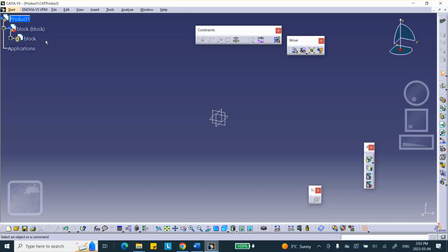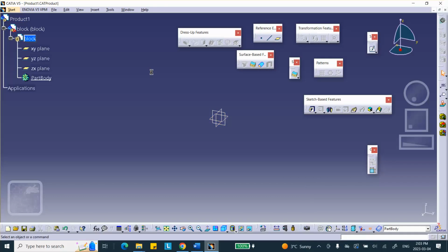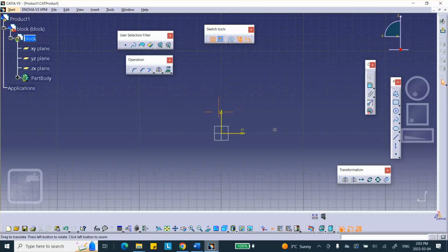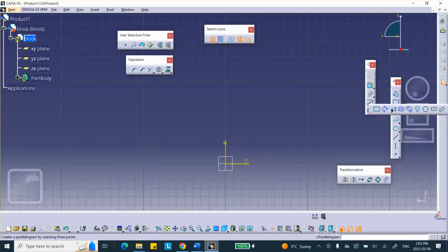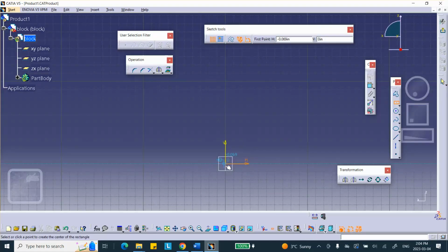Okay, let's make it. To make it, double click on this line here, which is a single gear. Double click, and on the convenient plane, on that vertical plane, I will sketch. Well, how about making a centered rectangle?